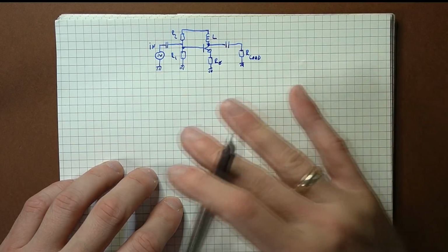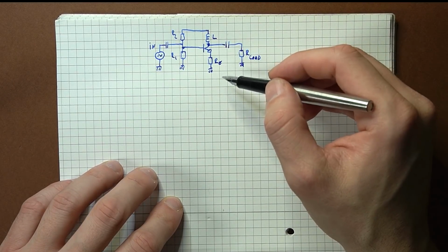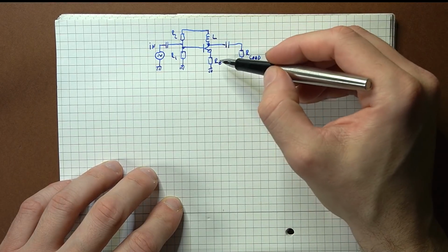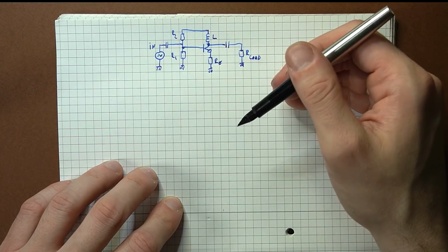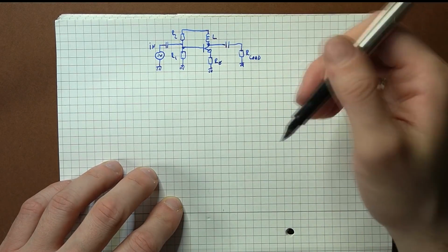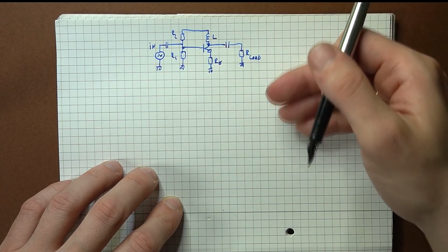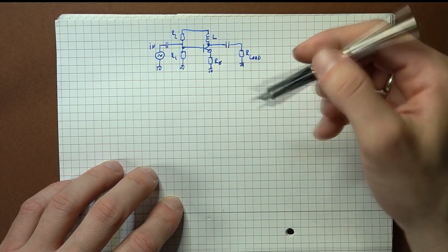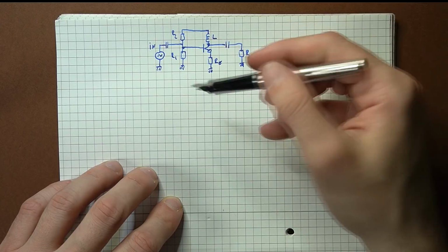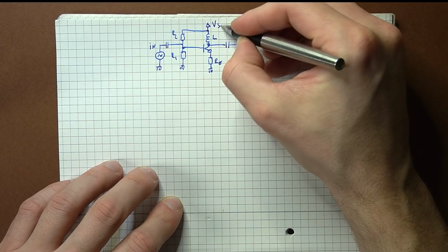Now, the general schematic will look something like this. So I will be using a common emitter amplifier configuration with a resistor network to set the bias point and an emitter resistor to stabilize the gain and provide negative feedback. Finally, an inductor will be placed in the collector to maximize efficiency. So this general topology should allow a maximum theoretical efficiency of 50%. And finally, we will have input and output DC isolation capacitors to isolate the input signal source and the output load, and a supply voltage.